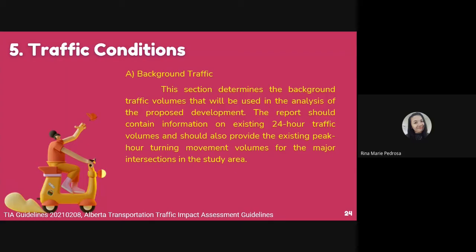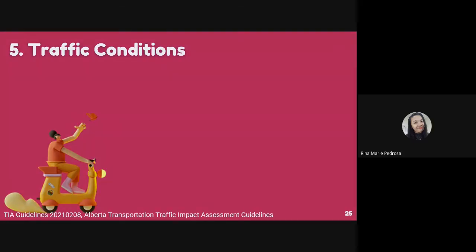In this case, volumes not identified as the peak hours for development-generated traffic would dictate storage lengths or lane needs. The TIA shall still provide an evaluation of the traffic volumes for the intersection's peak hours to ensure the improvements are appropriate to handle the system's traffic. Improvements that meet the highest traffic volume needs should be proposed.